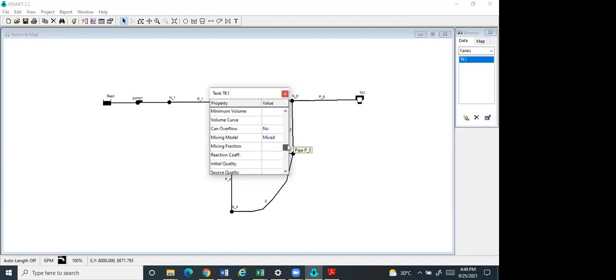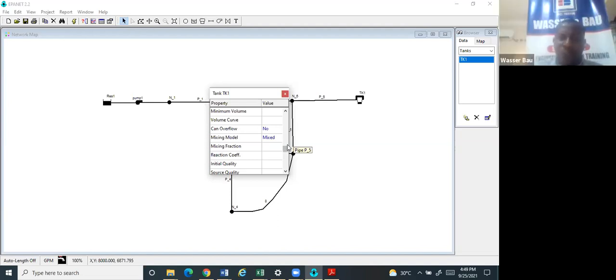There's a mixing level. These are advanced things beyond what we're doing. If you have 2 types of water, if you're getting water from surface tank and groundwater with different properties, and if you want to achieve a certain parameter, you can decide to mix 20-60, 80-20. So these are for somebody who is modeling quality.